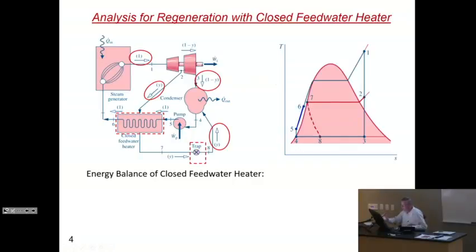And then once we are in 8, we mix with the steam that comes to 3 so that the final condensate at point number 4 here is saturated liquid, which then goes, like in a classic Rankine cycle, through the pump, 5 to 4, and then it is heated up partially from 5 to 6. The temperature is increased along this isobaric line.